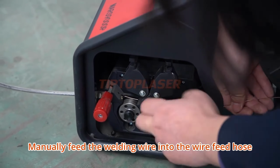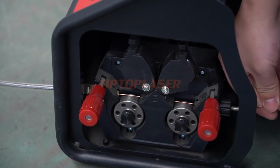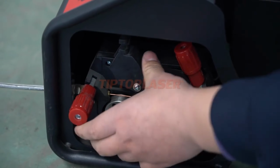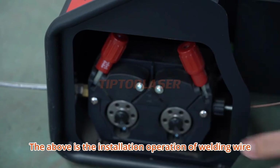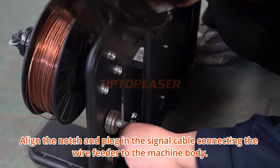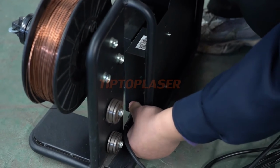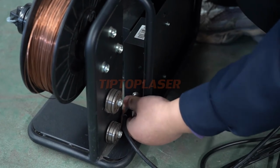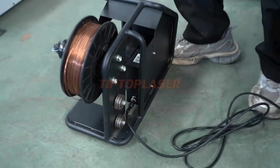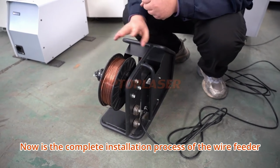Manually feed the welding wire into the wire feed hose. Lock the red device. The above is the installation operation of welding wire. Align the notch and plug in the signal cable connecting the wire feeder to the machine body. Now is the complete installation process of the wire feeder.